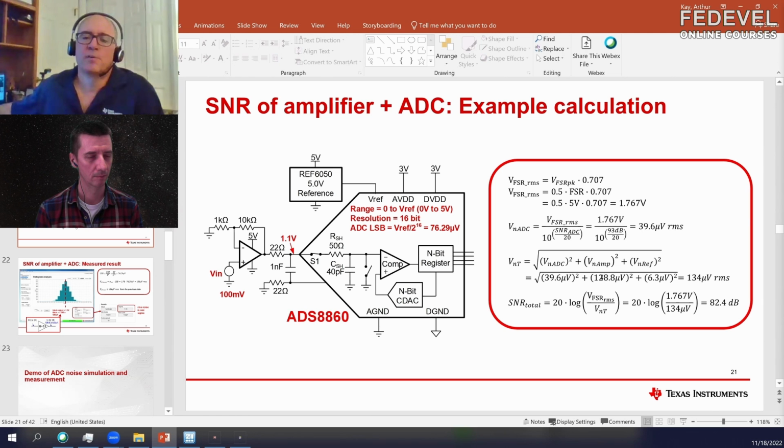In some cases, it might be the data converter or the voltage reference that's dominating the noise problem. And so you just have to attack the component that's the worst in the system. This is very interesting, because I would never say you can calculate it far before you actually design this circuit, and you can calculate it quite correctly and realistically.